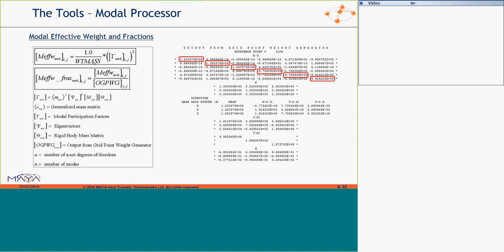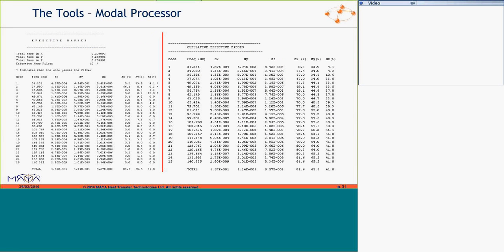What units do you typically work in? For me, back and forth, depending. Well, if you define NX, it will allow you to define your masses in pound mass if you're using imperial units, and does all this for you. But if you ever run into a model with a weight mass parameter in it, which does the same thing, then this gives you a bit of the background as to why it exists and where it's used.